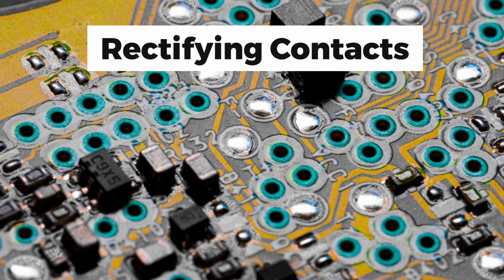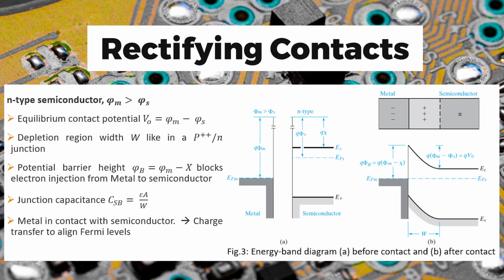First we will discuss the n-type semiconductor. To form a rectifying contact, the work function of the metal should be greater than the work function of the semiconductor. When a metal with work function phi m is brought in contact with a semiconductor having work function phi s, charge transfer occurs until the Fermi energy levels are aligned to each other, as we can see in figure 3. Here there are two figures. The first is the discrete case when the metal is not in contact with the semiconductor, and the second is when the metal is brought in contact with the semiconductor.